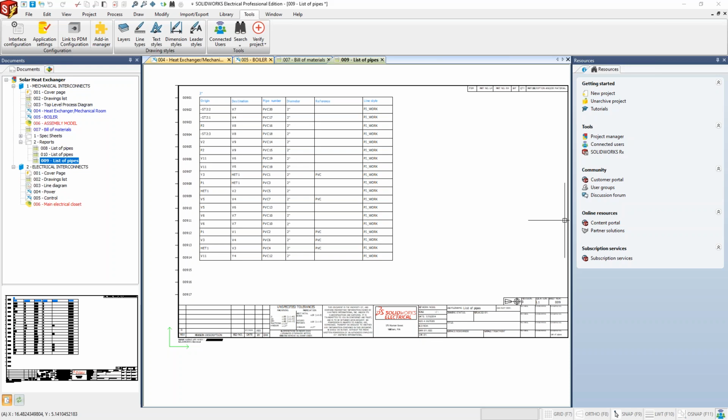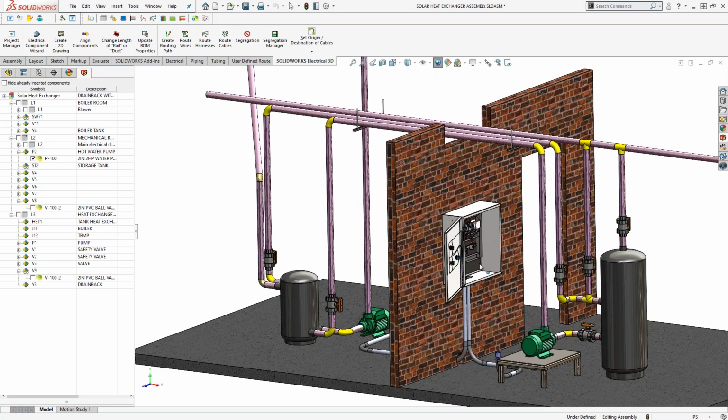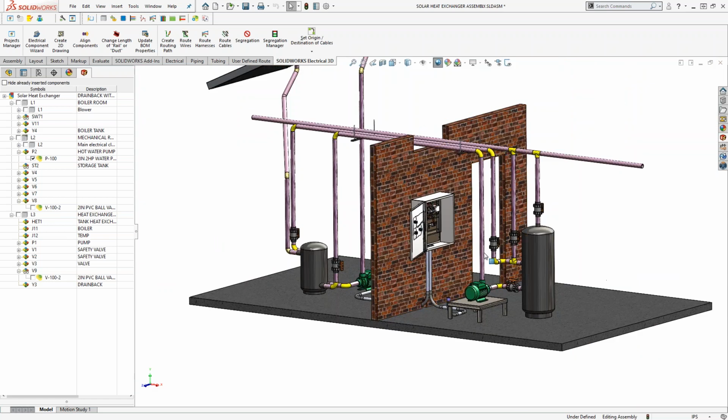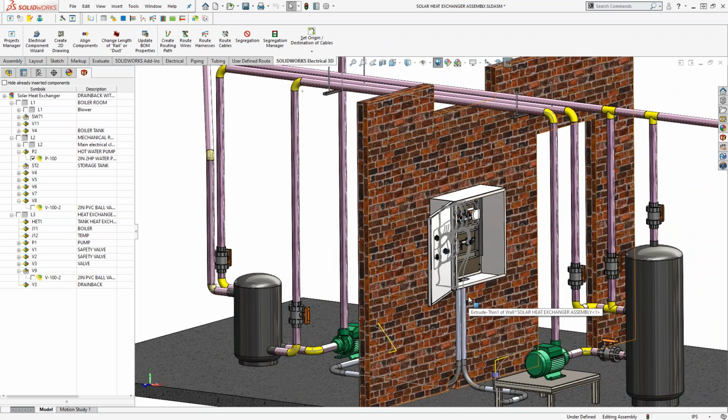But I think overall, one thing I didn't really show, which I can real quick, is we see here I do have an electrical panel, right? So in order to route things up through under stairs or along the side of the stairs or in a ducting or in this case here I have my pipe hangers, we have what's called an EW path or an electrical path that I want to follow. This is mainly for routing electrical wires or hoses that we want a specific path for.